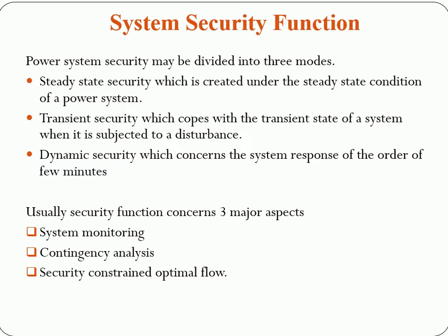In the power system, the equipment is usually protected by automatic devices which can make the equipment quit the system immediately once it operates out of its limits. The event may be followed by a series of further actions and cause other equipment to be disconnected from the system. This is called cascading failure. If the process of cascading failure continues, then the system will suffer from blackout, which means the whole network or the most part of it may completely collapse. Thus, it is not sufficient to merely maintain a system in the normal operating state. We need to specify security for each system to withstand disturbances under distinct conditions.